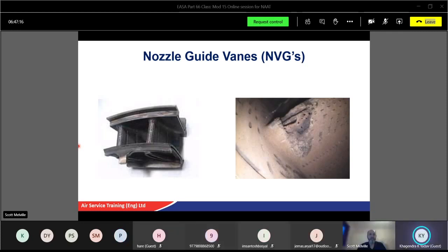To guide the hot air to the turbine, and accelerate the gas as well. So if a lot of them are missing, they're not doing the job. Yeah. So a big argument with the bosses there, and eventually won, thankfully. But it was safety. If the NGV totally failed, then the centre part would have hit the turbine, broken the turbine, and the engine would have blown up. So it was quite an essential part.